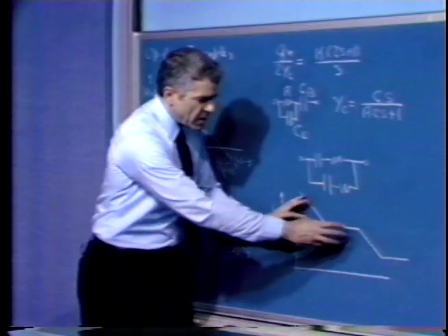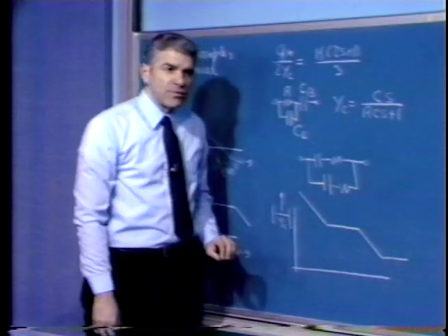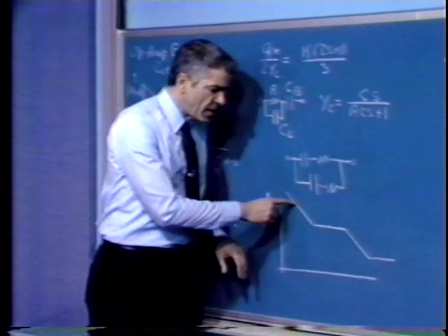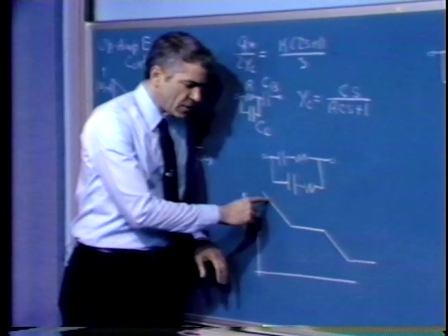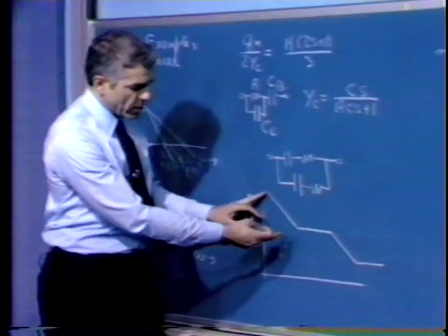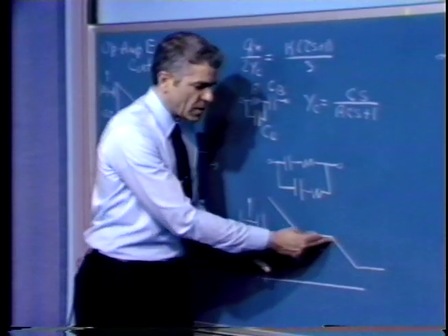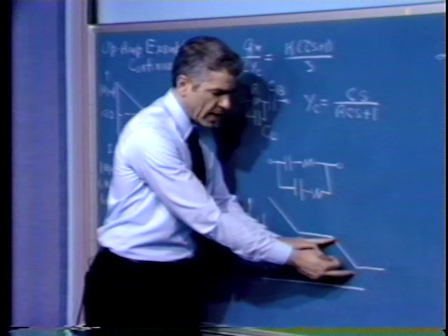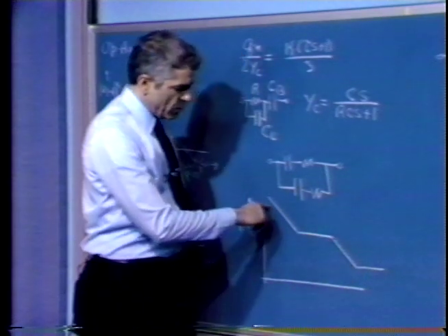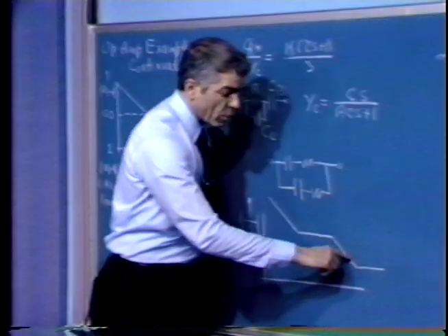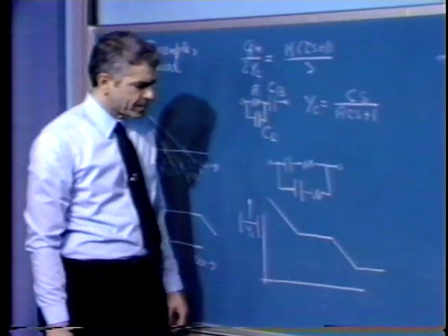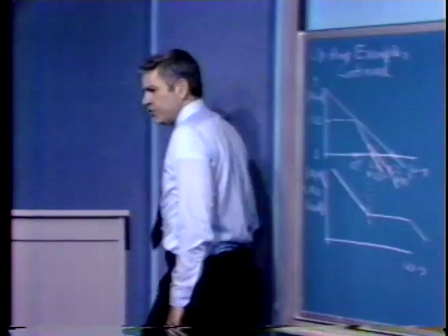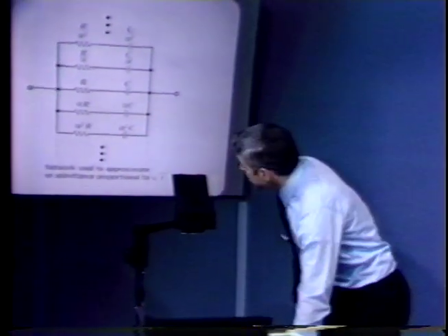And if we space the poles and the zeros associated with this transfer function closely enough, we'd begin to approximate a 1 over radical s roll-off. We'd roll off as 1 over s half the time on logarithmic coordinates, be flat half the time, 1 over s, and so forth, and begin to approximate a 1 over radical s roll-off. So what we would choose to do is use a network that looks something like this.